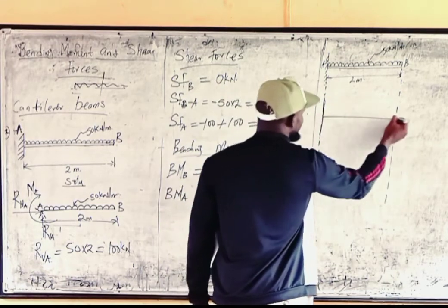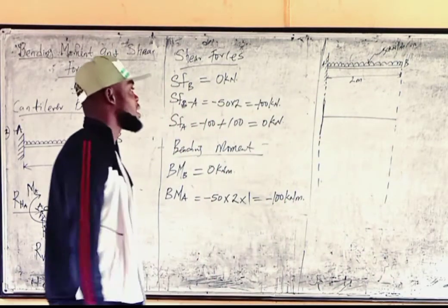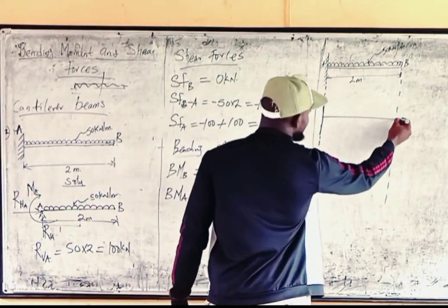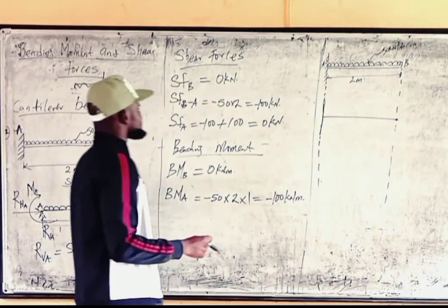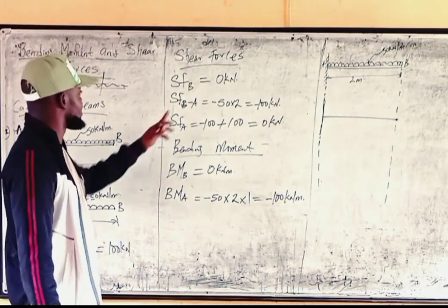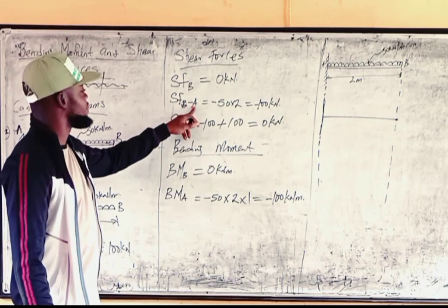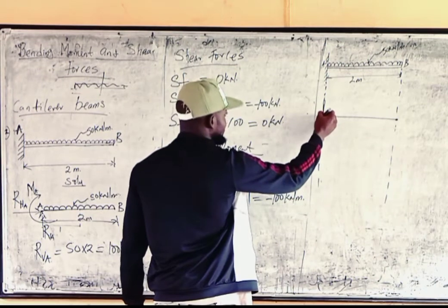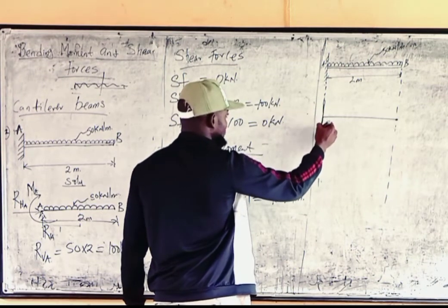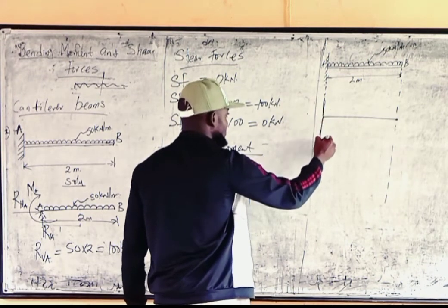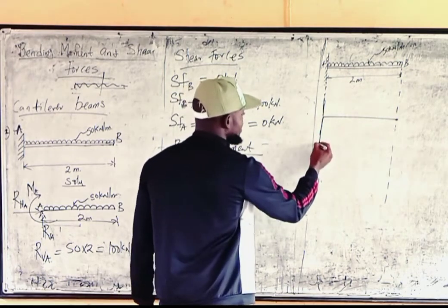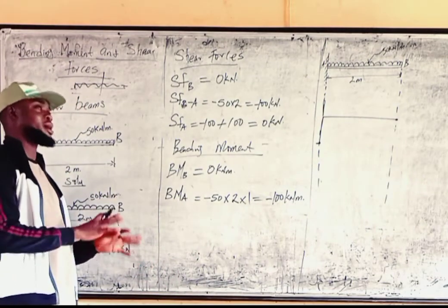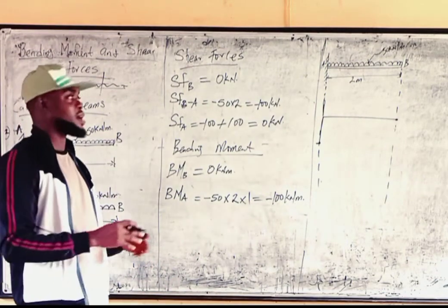So you draw the beam as the horizontal axis. And let's check how the shear force is distributed. At point B, the shear force is 0. Then from B to A, the shear force moves to minus 100. So we're going to mark out minus 100. So 100 will be here, because it's the other side. Now for shear force, we follow something like the normal Cartesian coordinates.